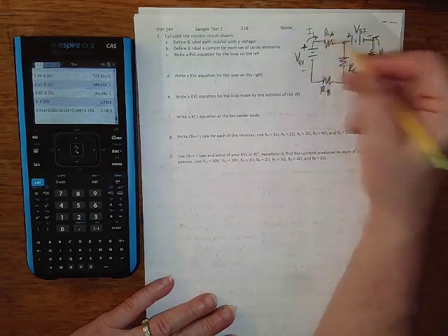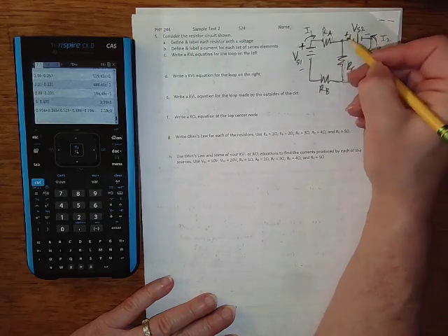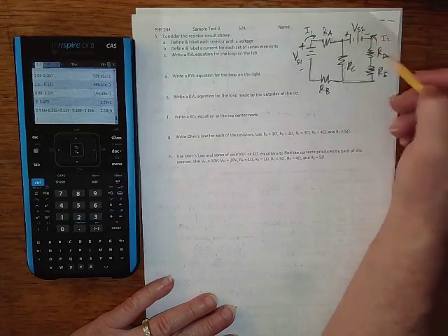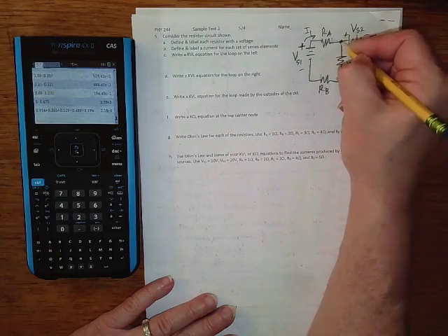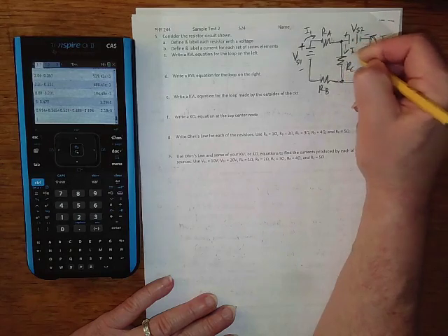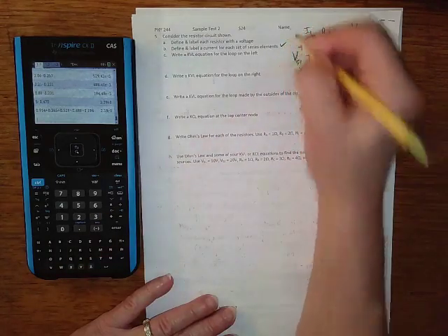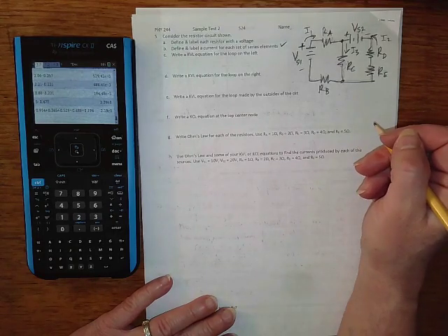There's only one current in this branch, only one current in this branch, and so I2 needs to go this way, right? It needs to go up, because drawing it over here, it comes out of the plus, into the minus. In this branch, I2 needs to be going up. Same thing here. And then thinking of the currents at this node, if I2 is coming in and I1 is coming in, I3 must be going down in the center. That's kind of actually doing part B first, but that gives us a good sign convention for the currents because of the sources. The sources are the drivers, and so if we want to get everything positive, it's good to start with them.